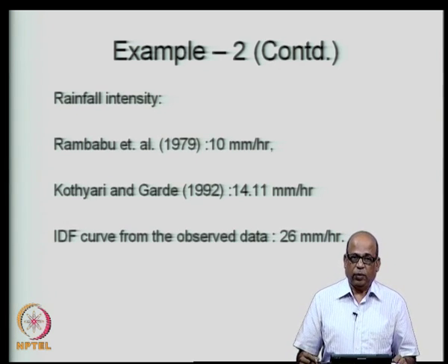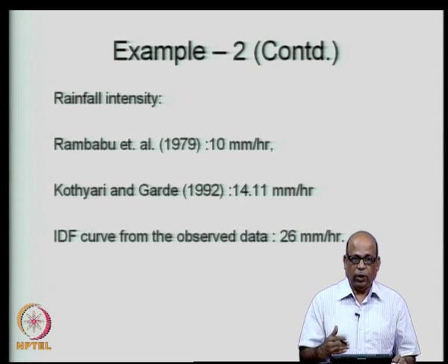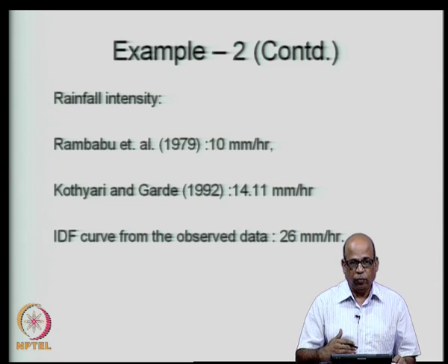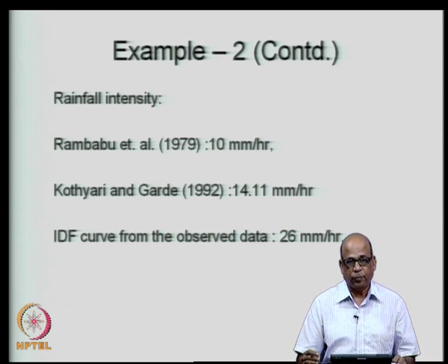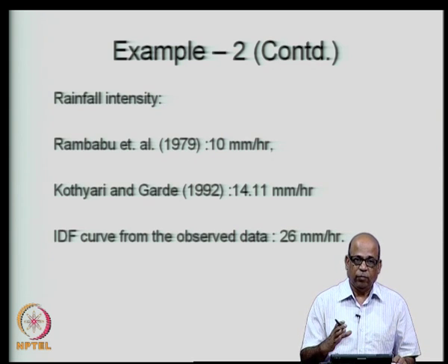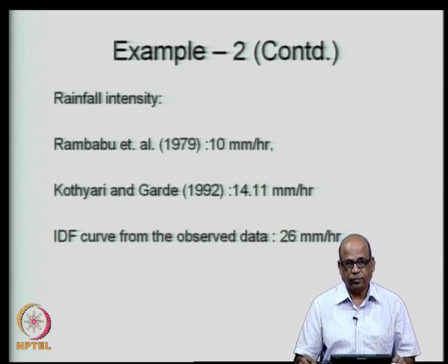And therefore, when you are making a hydrologic design today, and the design is supposed to serve you for the next 30 years, 40 years, etc., you must have a mechanism or a method by which you should be able to assess whether your IDF relationships can be held constant or they need to be changed as time progresses, and therefore, use certain correcting factors for use in the hydrologic designs.